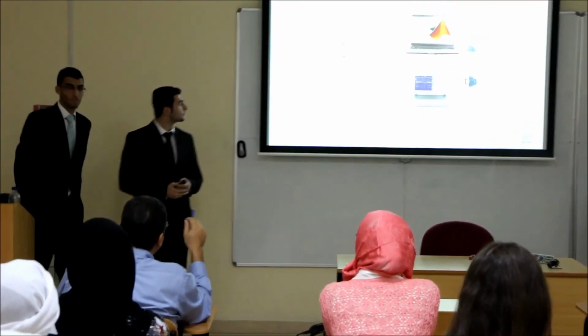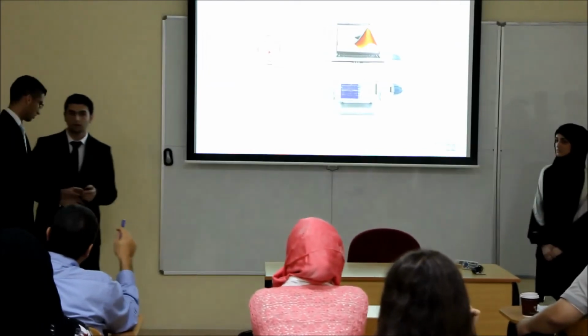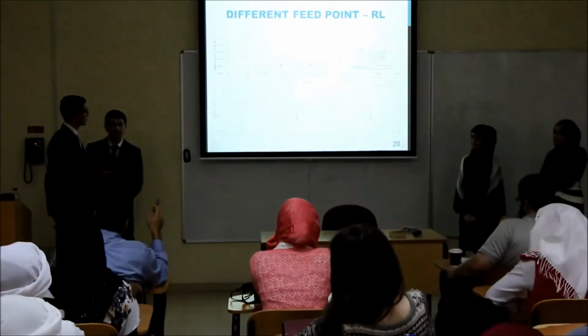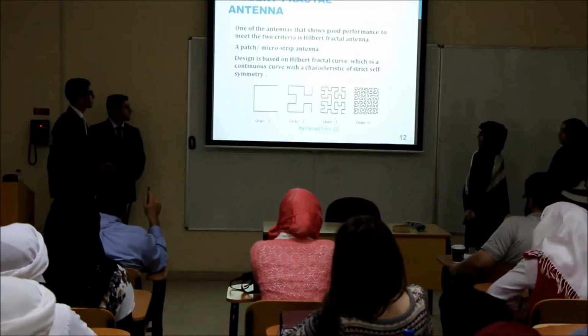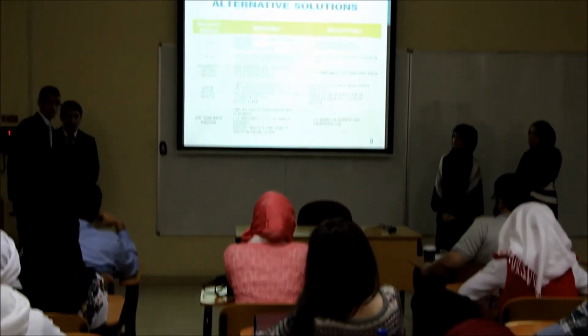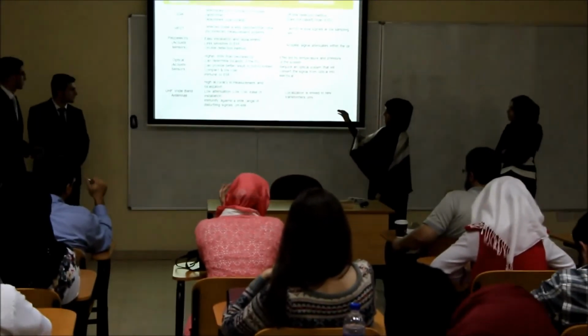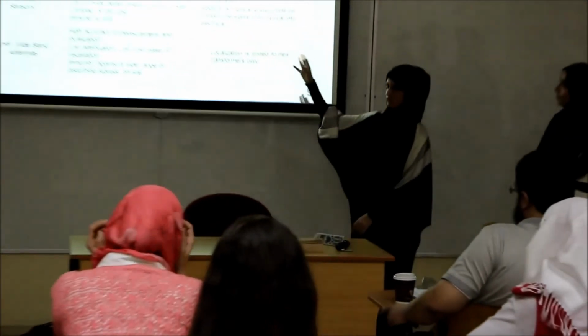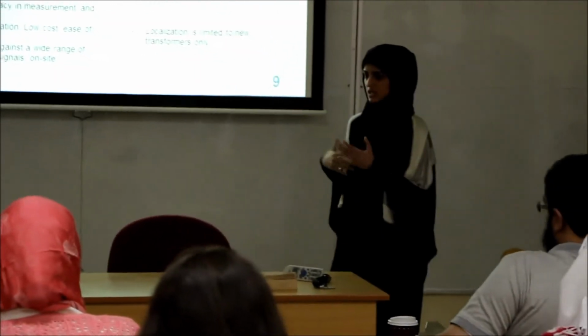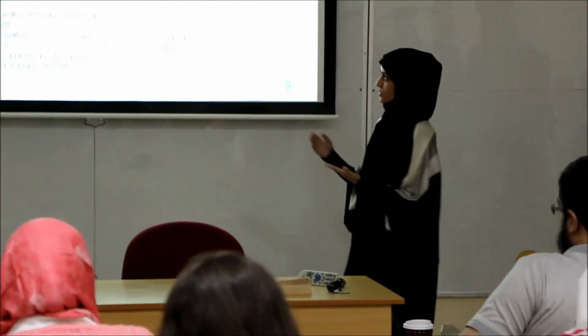The current solutions for using antenna, how different is your proposal here from the current solution using antenna for detecting partial discharge? The UHF wideband antenna is online, and DGA is offline, so that's limited because we want the transformer to be continuously monitored. So we disregarded the DGA.